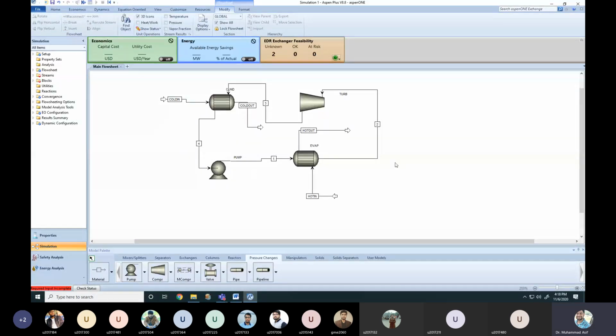So that means this is our model. Like from the evaporator, I mean the liquid refrigerant from the pump will enter into the evaporator. And in the evaporator, what we are giving is the hot water, let's say. And this hot water can be produced from solar energy, it can be produced from the condensate. So there could be any source of heat. Let's assume that we have some hot water and that hot water, when it enters the evaporator through the heat exchanger, then the liquid refrigerant will be converted into vapors. So those vapors, when they enter into the turbine, will produce power, right?